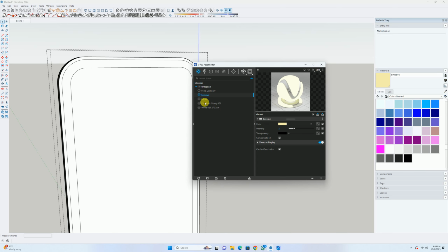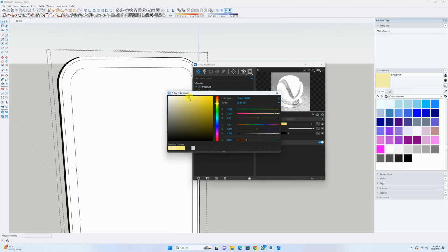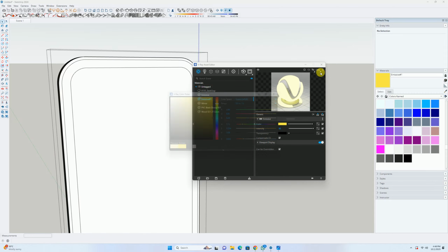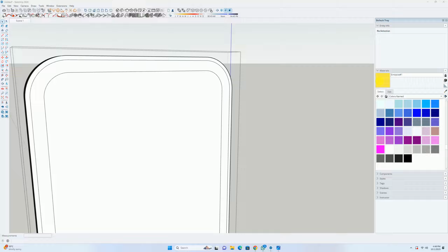For the back, I'm going to use another image material because I increase the intensity of this image material. So I'll click on duplicate, and from here we'll increase the intensity of the light. We'll close this.